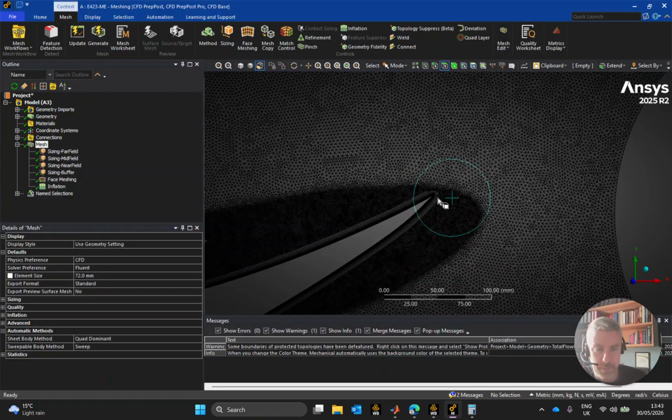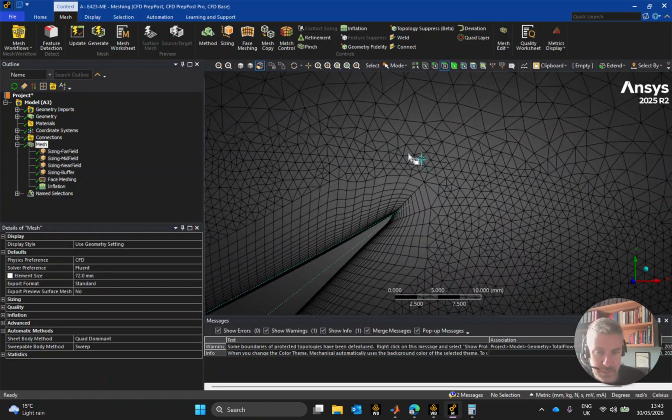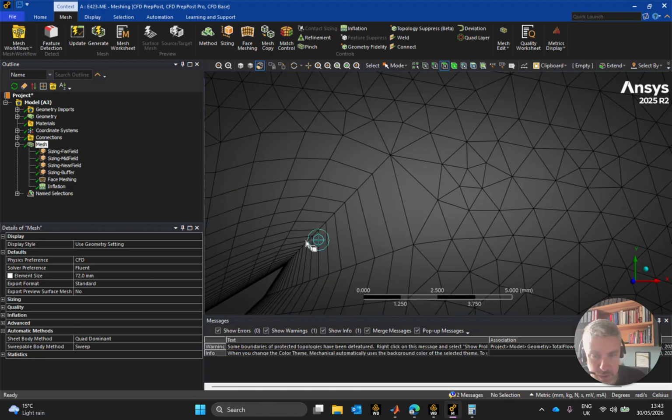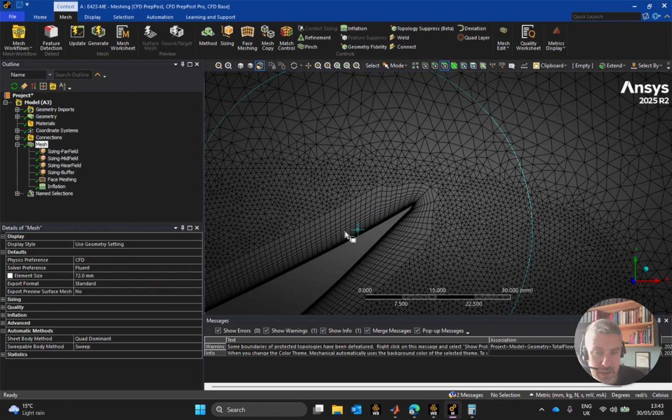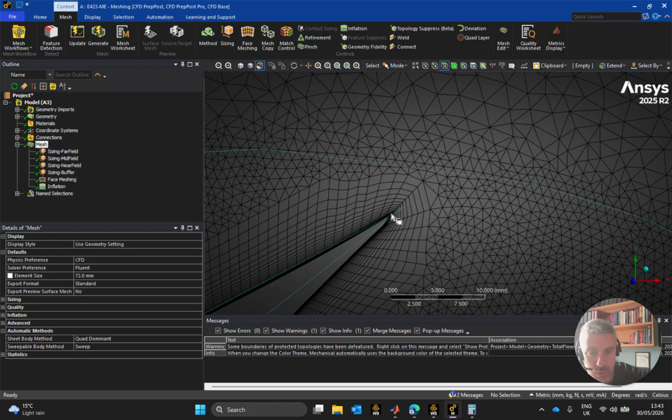So this relationship should always be the same, right? Because every time I rotate, I'm going to rotate my buffer and this inflation layer together, because what I'm really looking to try to do, everybody, is protect this inflation layer. Right? You know, it seems very skewy there, but that's what you're going to get when you're coming into the point. I want to protect that inflation layer so that when I rotate it, I should be rotating the inflation layer, them cells on the boundary. I would have been otherwise rotating them into all them triangles, and they would have skewed more potentially, especially at that trailing edge.